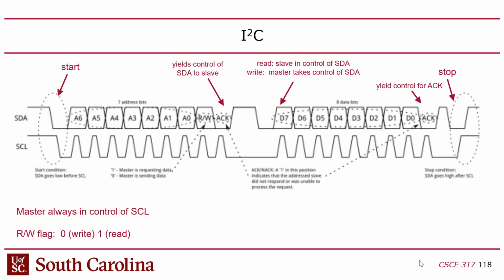Remember that if you don't do anything with open drain, the signal is logical high, but if either side were to pull it down to 0, it's going to stay at 0, regardless of what the other side wants, right? It gives you a way to wrestle control of something away from someone else.